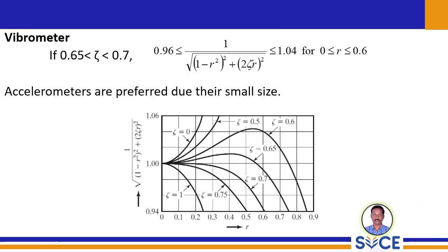Looking at our earlier discussion on vibrometers, we established that they work best when the operating frequency is significantly higher than the natural frequency. However, in the present slide I have a different perspective with respect to the accelerometer. There it is the vibrometer case, here it is the accelerometer case, focusing on lower frequency values. You can see all the r values are less than 1, and the different damping values are carefully chosen between 0.05 and 0.7. The magnitude remains almost equal to 1.